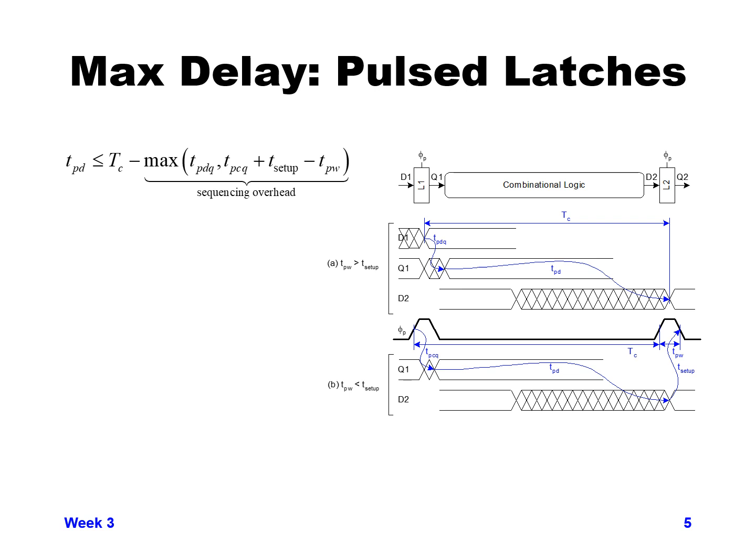that means we basically need to set up before, well, normally we're talking our cycle time is to the rising edge of the latch, from rising edge to rising edge. But since we get this additional time through the pulse width of the latch, the total amount of time that we have is the setup time minus the pulse width.